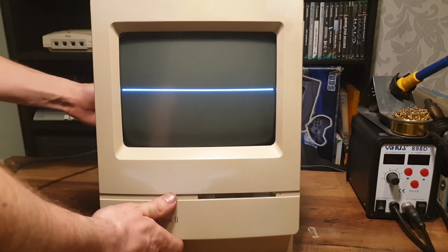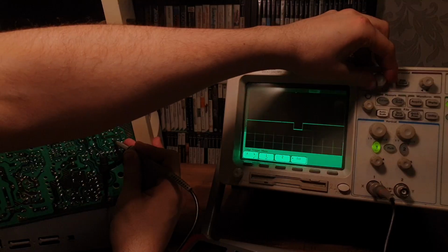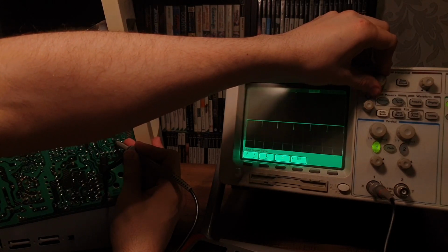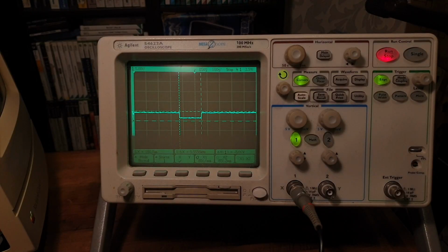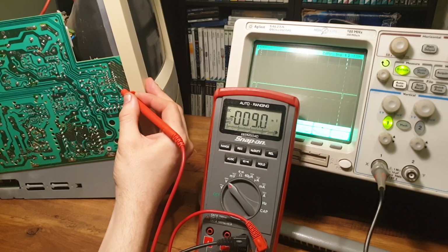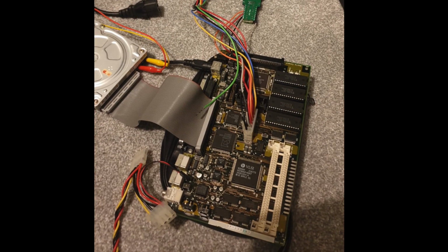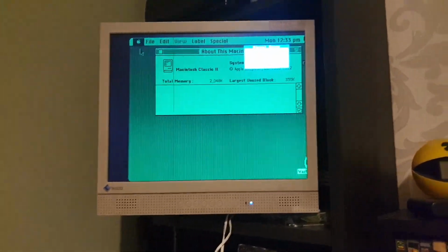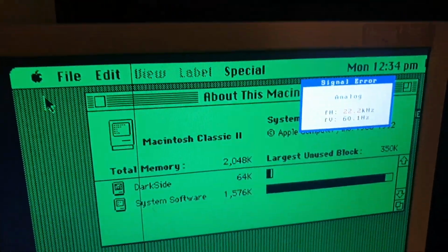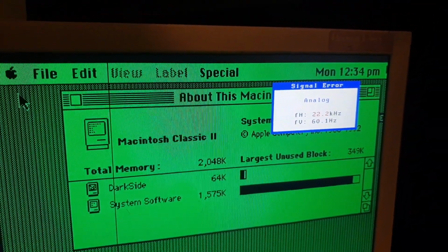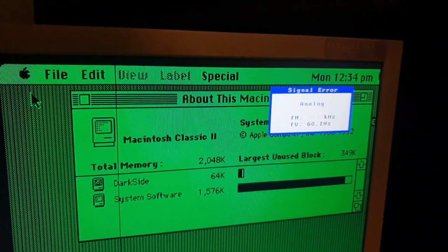No. Not only was I annoyed by this outcome, but I was also confused. I had thought that the new chip was faulty, but then I decided to double check my measurements. Even going as far as making a custom harness to use the board on an external screen and PSU, which works if you're using a 22kHz capable monitor. Seeing it work meant the logic board should theoretically be fine.